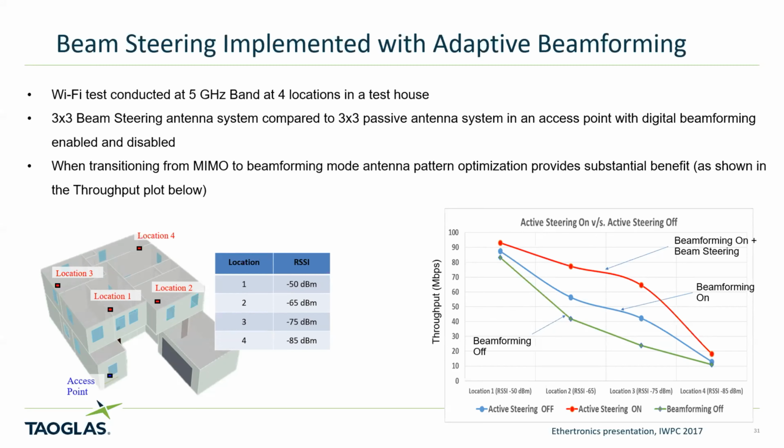I know, it's a good question. In other words, if you're going to confine yourself to a smartphone, it's very hard to maintain isolation between the two antennas at the sub 1 gigahertz bands. And if you attempt to add more, in my opinion, the system collapses. You really can't do it because you're degrading the efficiency of all the antennas because they're coupling too much. At the higher frequencies, you're getting better performance off the main and secondary antenna in a smartphone. And at some of the higher LTE frequencies, you could add a third antenna and probably maintain acceptable isolation.